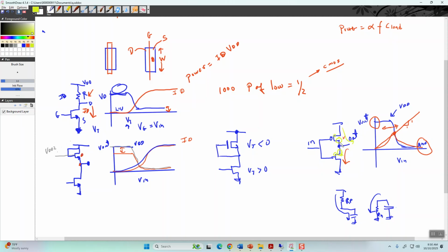But there are other gates that I'm about to go into where you really count up the number of drains, and you'll see how that works in a bit. But that C load is every capacitance that gets charged and discharged on the entire chip. Sometimes you have a capacitor out here that's really just the equivalent capacitance of a long wire that's being driven across the chip.